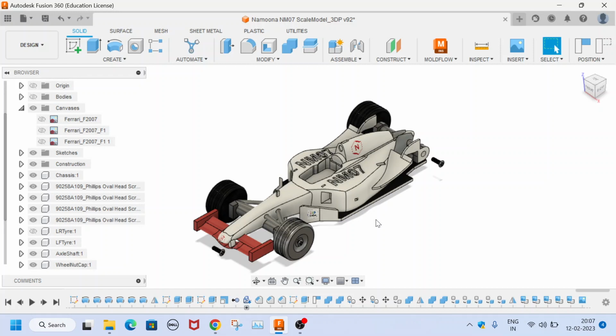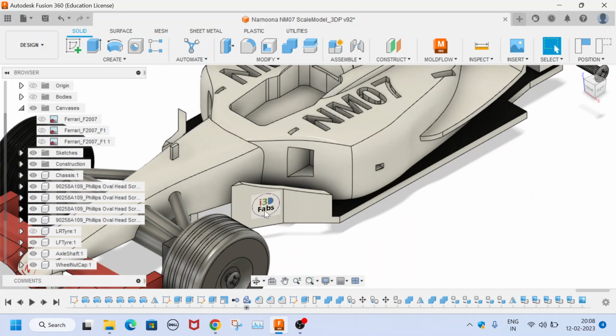Typically for academic research, I think IIT Bombay and IIT Madras have a wind tunnel. You can place your 3D printed F1 car there and analyze for the downforce and drag, and you can not only analyze the complete body, but you can also place sections. For example, if you wanted to analyze the flow of a particular component like a front wing, or a simple element, for example how this barge board will channelize the flow around the front wing and deflect some portion under the floor and inside the side ports.